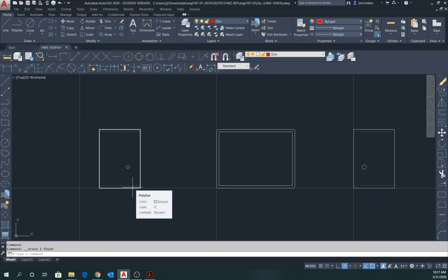Now, if you've created your print properly, you shouldn't actually have to change any dimensions. From the dimensioning toolbar, we can do vertical and horizontal dimensions with this tool here. So if we click here, we can put in the first dimension just by doing this. We click on this corner, then we click on the center hole, and then just pull down. And that'll create the dimension.